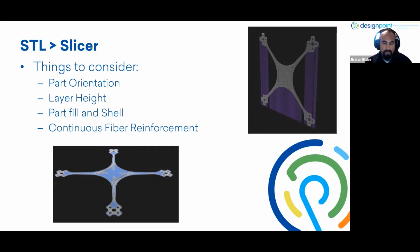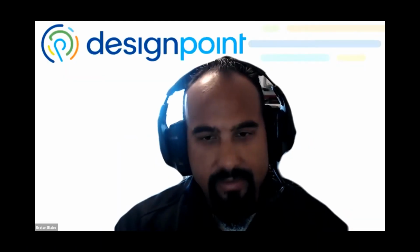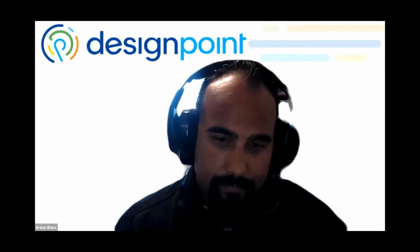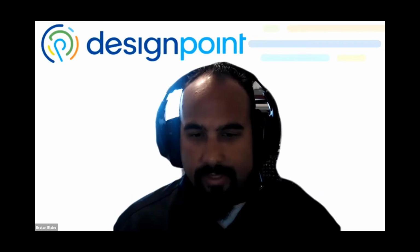So what we went with is the lower left-hand corner. As you can see, if that frame was just laying flat on a table, that's exactly how it's laying on the printing bed. It was laying completely flat, coming down from the Z-axis, your nozzles going back and forth and printing those layers. So we didn't need to generate any support material for that. We had minimum layer height. And with our part fill, we didn't have any part fill in this orientation because the print's going to be completely flat.